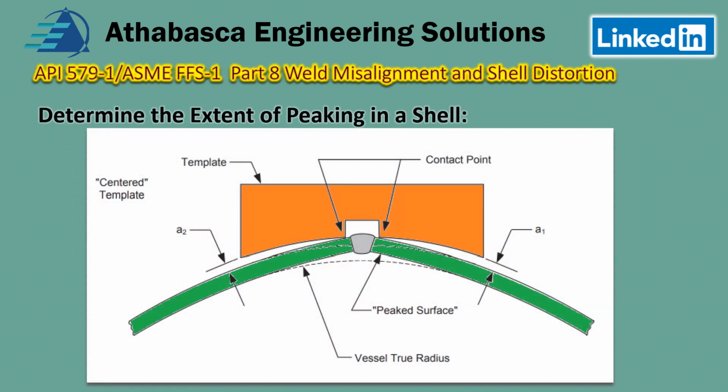A method which is recommended by API 579 for determining the extent of peaking in a shell. In this case, we have a template, and we have a couple of contact points. From what I remember, this radius matches the vessel true radius, which is shown over here. So in this case, when they put the contact points down, which is outside of the weld area, and you balance them equally, you're going to get an A1 value here and an A2 value over here.